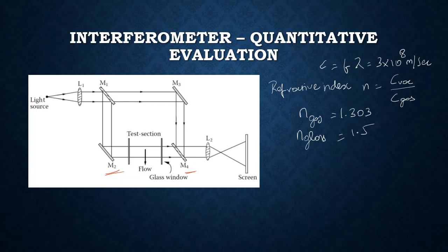Now we have acquired the values of refractive index. Now you have to acquire the values of density, right? And then you should be focusing on density. What is the density of that particular point? You are seeing or visualizing the flow across any type of model where a sharp density change or high density flow occurs in between the corners. That is, if you are keeping a wedge body inside the high speed tunnel, we will have sharp corner occurrences like oblique shock waves. So we have to find out the density of that oblique shock wave.